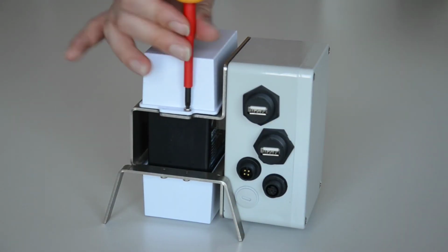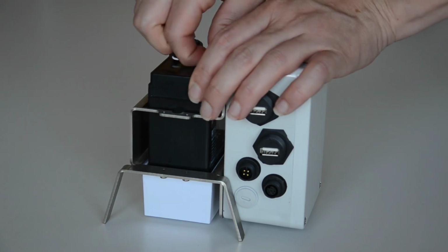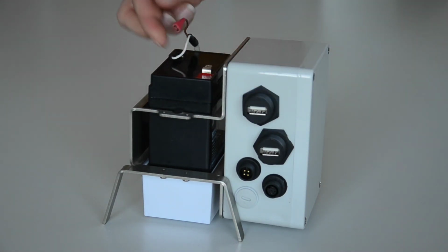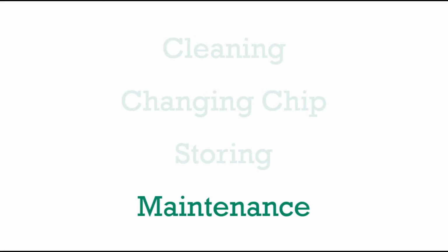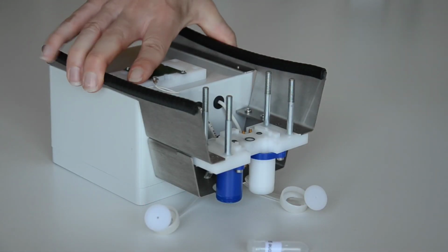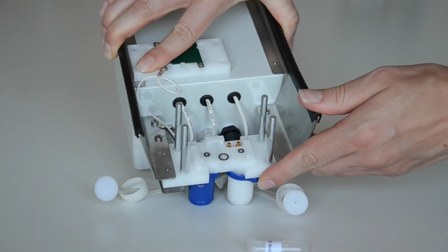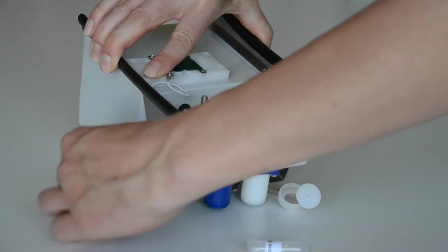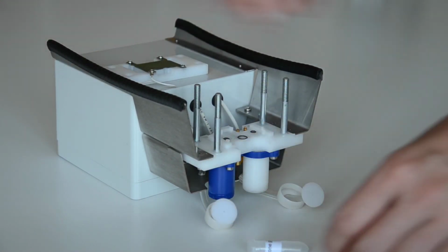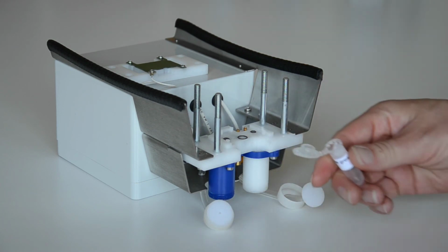Also disconnect the hub from the power and interrupt the connection to the battery so that it cannot be discharged. These free sealing rings must be regularly covered with a small amount of silicone grease, so that they do not become porous. Otherwise the tightness is no longer given and a leakage occurs.